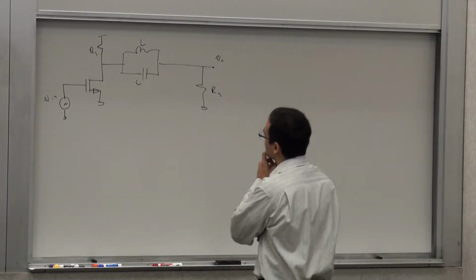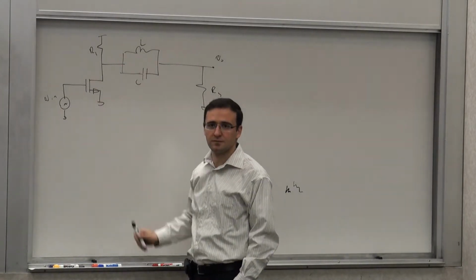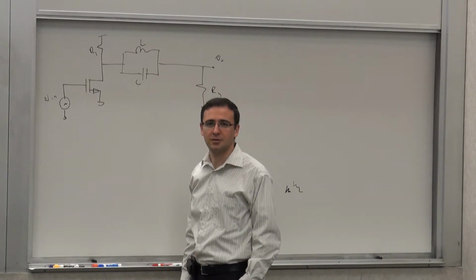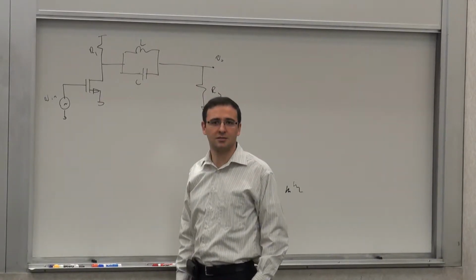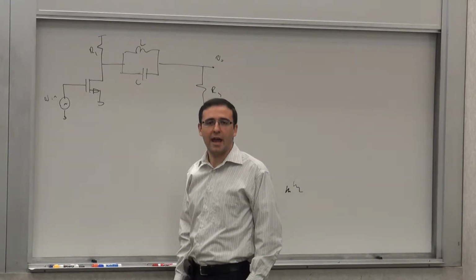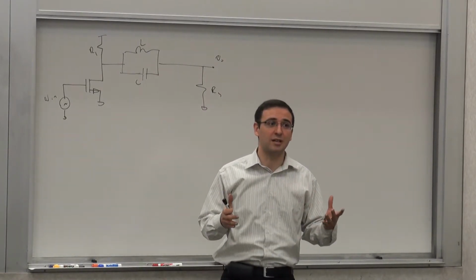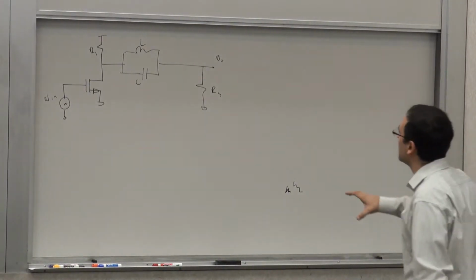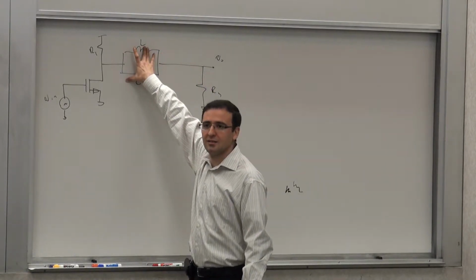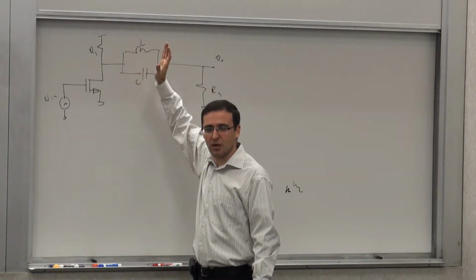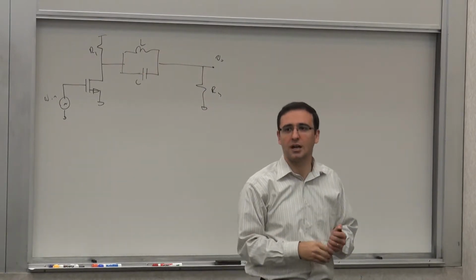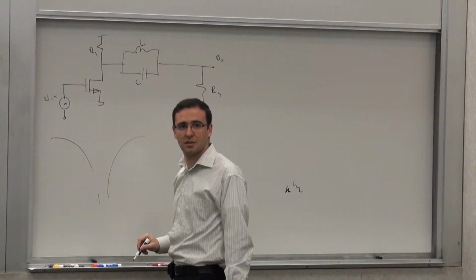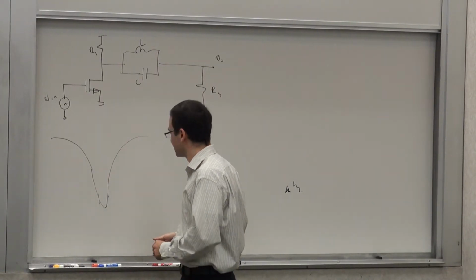Think about high frequency and low frequency. At very high frequency, does the signal go through? Yes. What does it go through? It goes through the capacitor. At low frequency, it goes through the inductor. And there's some frequency at which these two impedances, the admittances, can cancel each other out, and then this can present a very large impedance. And that frequency basically can just become a band stop or notch, as you pointed out. So I expect the transfer function to do something like that.